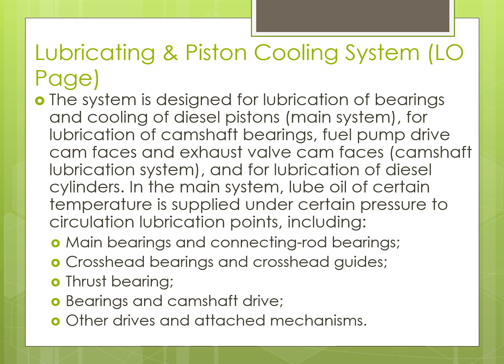Lubricating and piston cooling system. The system is designed for lubrication of bearings and cooling of diesel pistons, for lubrication of camshaft bearings, fuel pump drive cam faces and exhaust valve cam faces, camshaft lubrication system, and for lubrication of diesel cylinders.